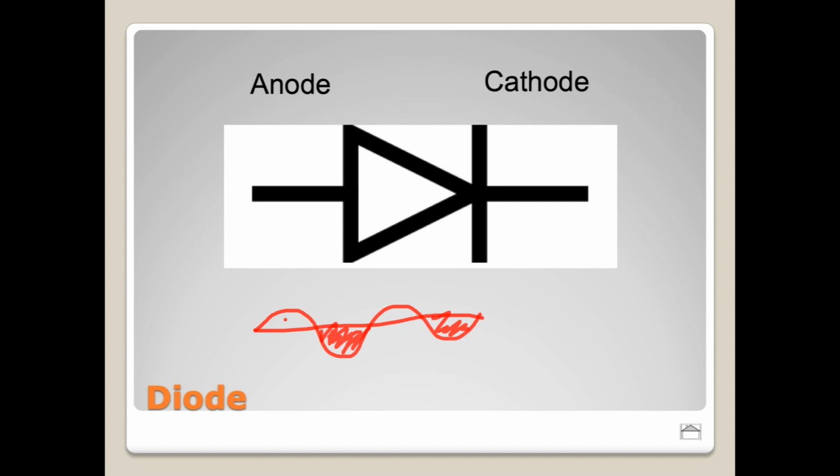Again, if you have a really vintage tube guitar amp or a really vintage piece of equipment, the diode that's in there is actually a vacuum tube diode, and it is doing half wave rectification. It's a very inefficient form of converting from AC to DC, but hey, it's better than nothing. This was the original way that it was done, and the bridge rectifier is an improvement on that. But it's very, very inefficient. It's really hard to get a nice stable DC supply that way.